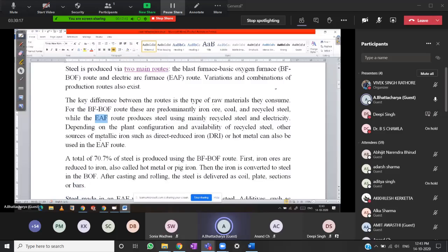Can you imagine? 50 hertz, when a heavy arc furnace starts, the frequency of this AC goes down up to 47 hertz. The load is in megawatts. This is not very popular here because in our country electricity is not very cheap and plentifully available. Okay.